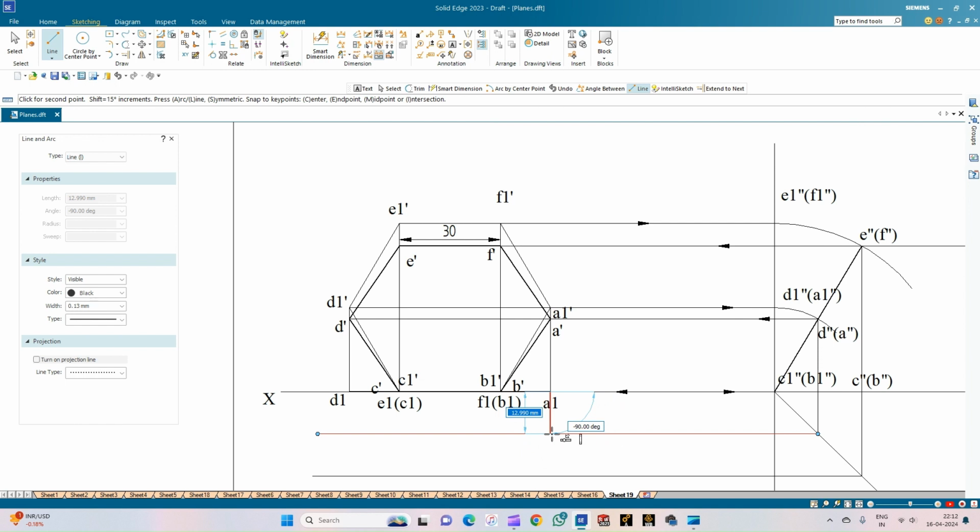So from A it is here, and then projection B is, okay, so B will be on the same line, B and C will be on the same line. D will come from this point to this line, so from D and A. Similarly, from E, I'll be having the projection line here, and next the projection line from F, and the side projection line from F. So now we'll complete the top view.